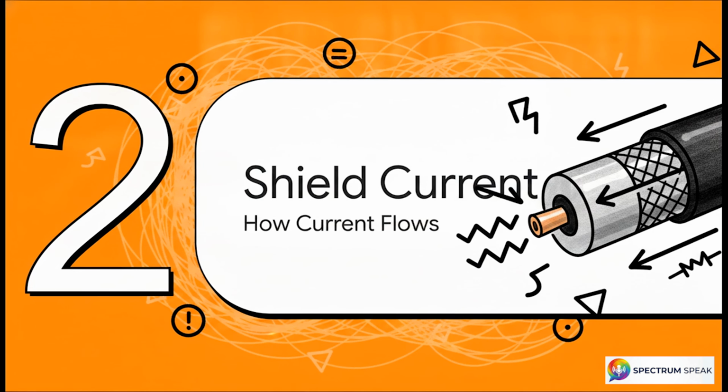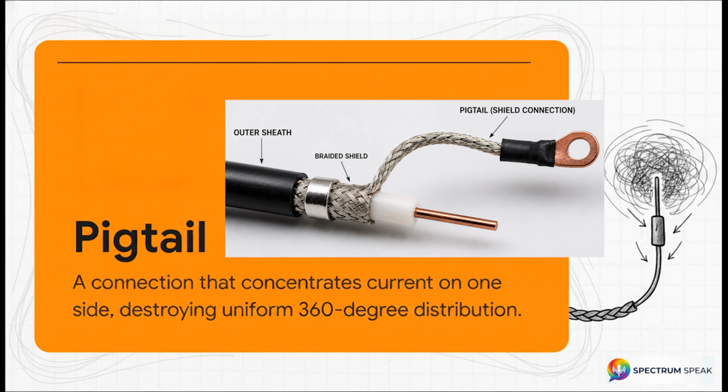Moving right along to Part 2, Core Concept, Shield Current Flow. According to electromagnetic compatibility expert Henry W. Ott, the magnetic shielding effectiveness of a cable depends entirely on one crucial thing: a uniform distribution of the longitudinal shield current around the entire circumference of the shield.